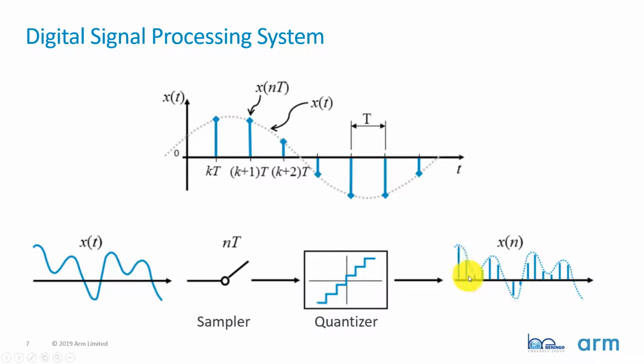Now, of course, it's possible in between our samples, the signal could be going all over. So we have to be very careful how we go about selecting our sample rate and making sure that we're not going to have any problems with the signal or that we misrepresent it when we're actually reading it in.